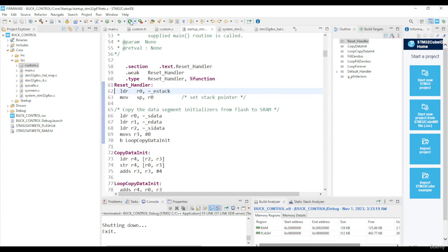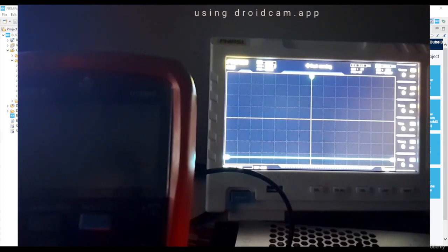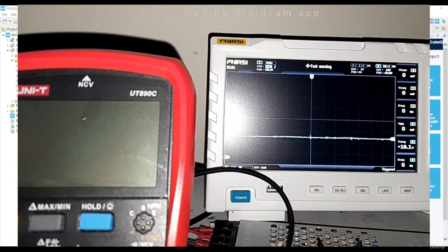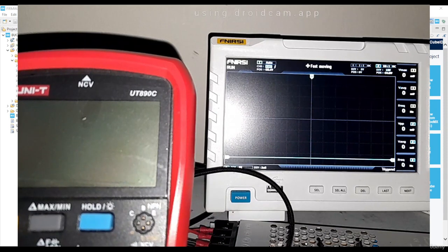Okay, change the coefficients and go back to it now. Let's do that. Okay, flash on, turn it on. You can see there's hardly any jumping up and down. It's just stable in that same state, with the exception of the switching noises. But everything pretty much is stable. Yeah, that's about what you need to do in that case to make it more stable, of course taking into account everything else.